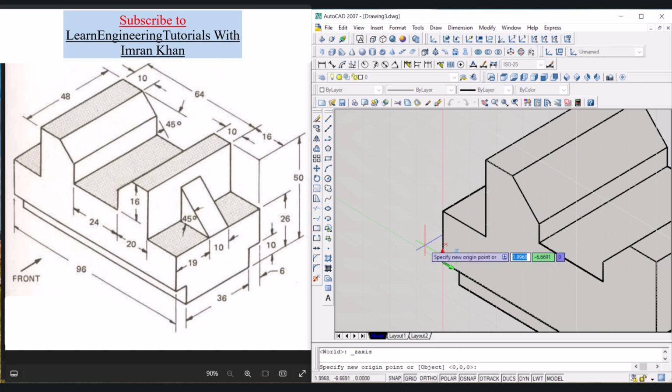Let the origin be the same, press enter. And now we have to select a point on the positive Z axis. So click on this line. And now this UCS looks okay to us.